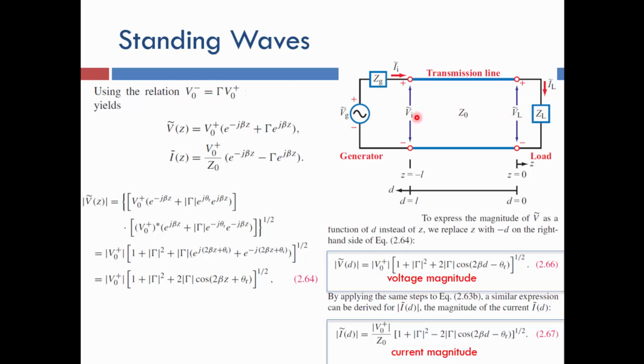reflected energy or power or voltage to the transmitted one. The voltage reflection coefficient is the ratio between the reflected voltage to the traveled one, or the reflected current to the traveled one multiplied by minus 1.